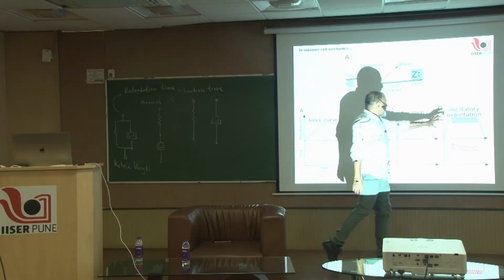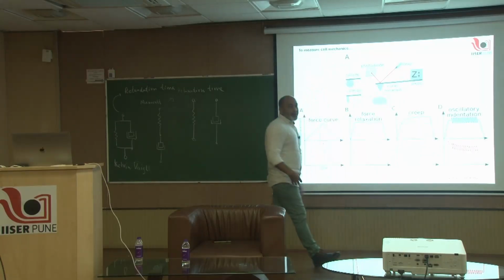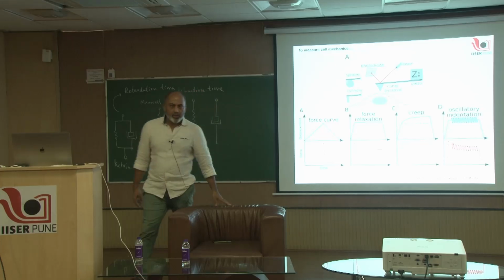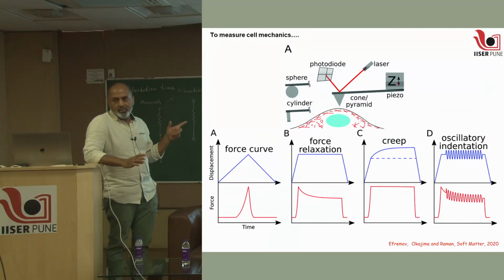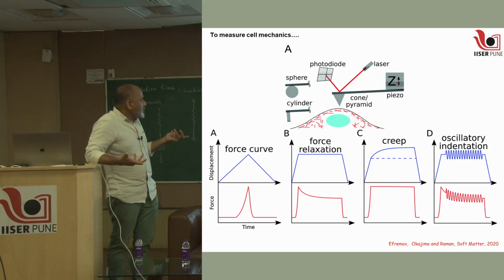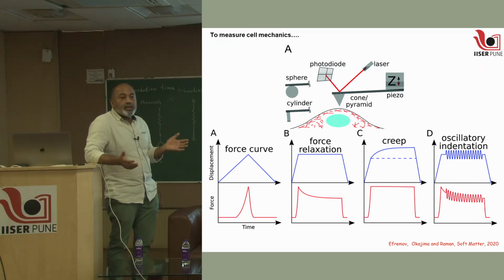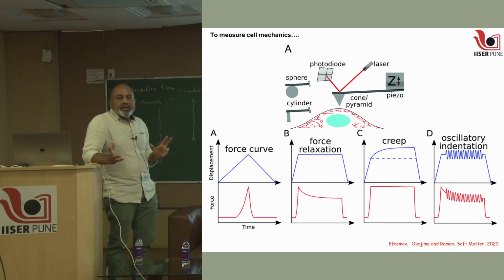This is the most common way rheology is done, and when you talk to rheologists, that is what they do. Other things are not very appealing, because sometimes the creep relaxations are so fast you do not catch them, if they are in milliseconds or microseconds. So what is good to do is provide oscillatory stress, measure the strain, and see the phase lag between strain and stress. This phase lag, called the loss tangent or tan delta, can be used to get G prime and G double prime.